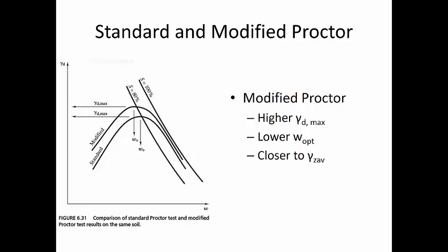And that's an important reason for the justification of looking at sandy materials using modified Proctor and clay materials using the standard Proctor, especially when the clay material is utilized for preventing water from flowing.